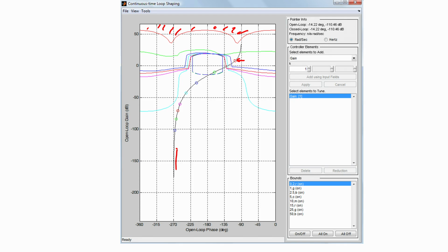And I discussed that this can be done in an interactive manner using this dialog box. For instance, we can start by choosing a proportional controller, and that proportional controller can be used to push up the overall gain, so that to start with the red circle is within the red bound, but then we might end up with a closed loop system that is unstable, and hence we can choose to pick zeros and locate the zeros such that the Nichols plot of the overall loop gain avoids the forbidden circle, and so on and so forth. Some of these steps were discussed by me in the previous design that we undertook, where we did 1 degree of freedom control design that took care of disturbance specifications.